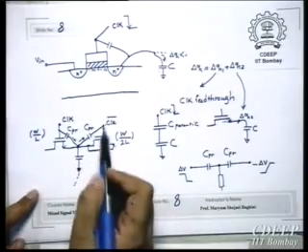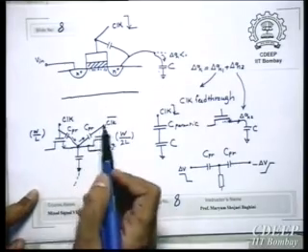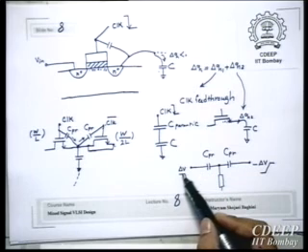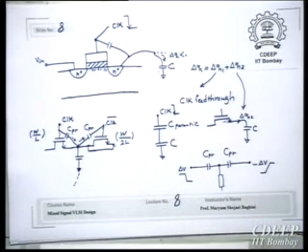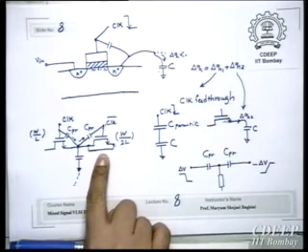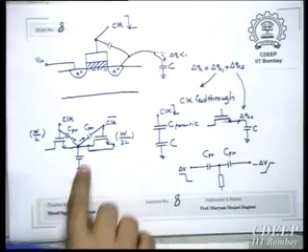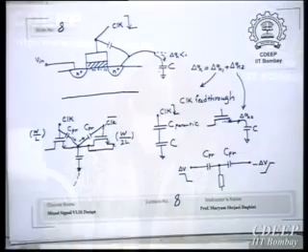Therefore, charge and discharge will always be through these two capacitors if they are completely matched. We don't mind whether the sign is positive or negative. This is an off transistor because source and drain are connected, therefore it behaves only like a capacitor connected between this node and the plug.